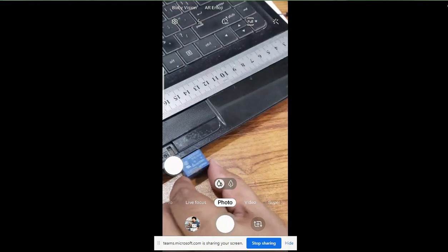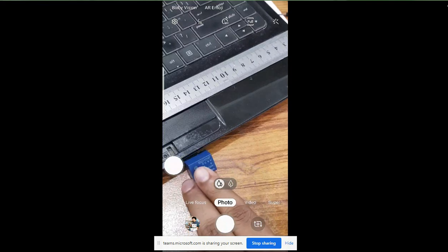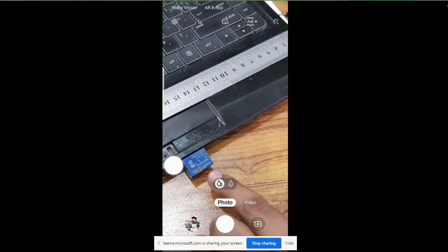As you can see over here, this is a DC 5 volt relay, and this is 5 ampere AC 125 volt, which means this relay can only work at 125 volt AC, not at 230 volt AC, because normally in our homes we have 230 volts. So this relay may not be enough; you can only use it for an AC voltage of 125 volts. Now this relay which I am showing you at present is a little different.